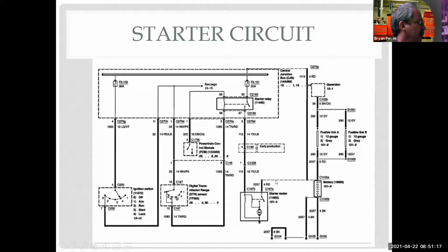So if I just go to the starter, I've got an open switch. Well, what closes the switch? Oh, some kind of contactor, relay, or solenoid. Okay, so I need to make this turn on. The ground for it is right here, which means it has to get power up here. So if I come up here, here's power.